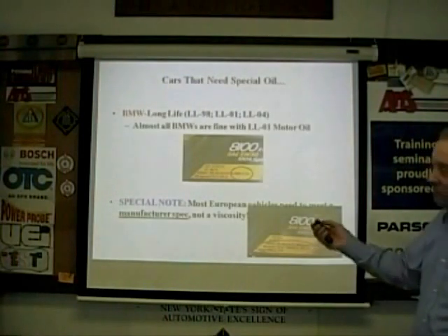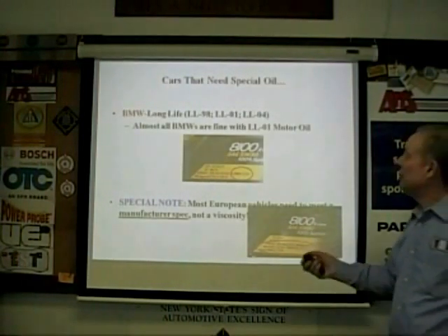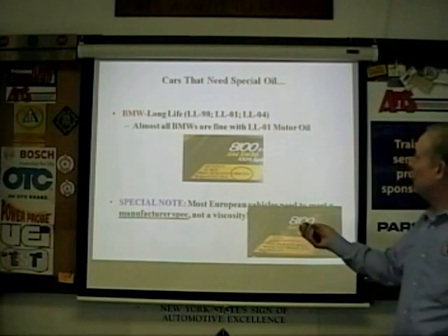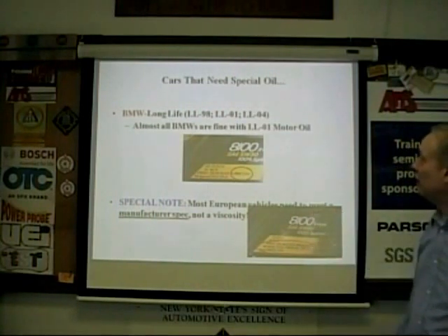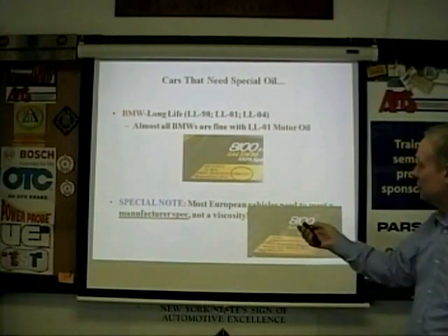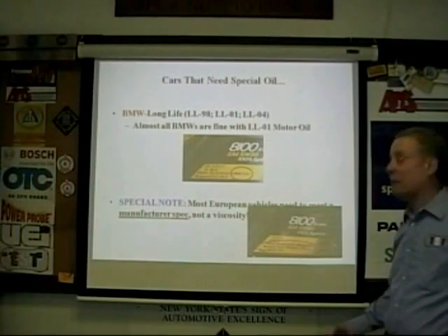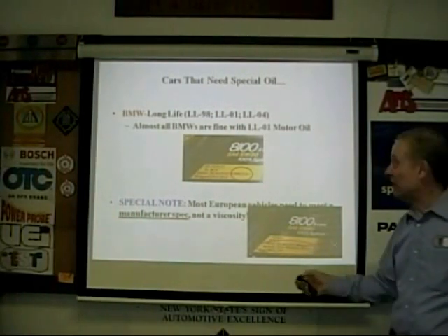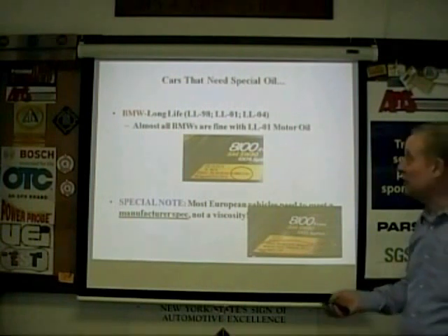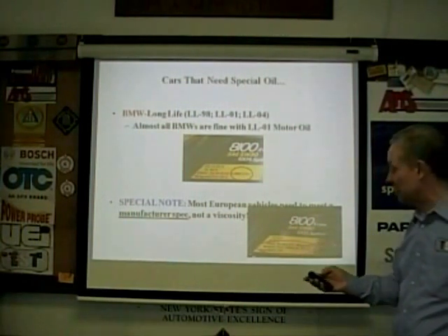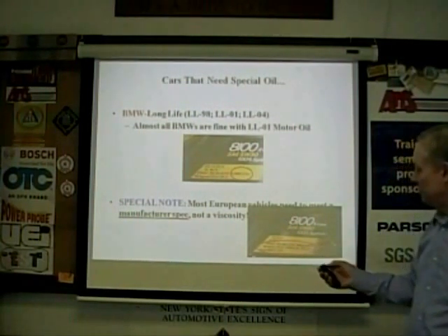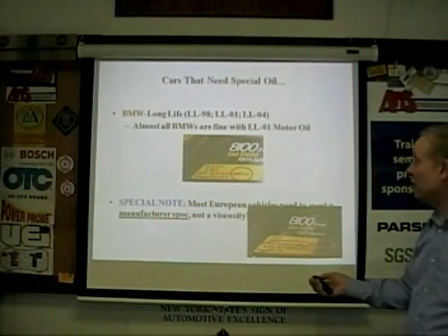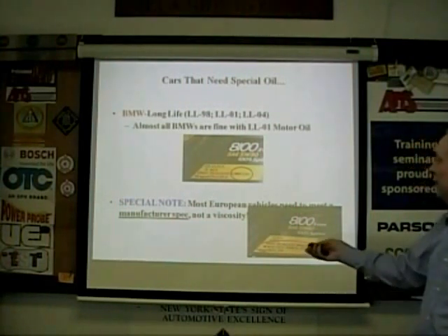Speaking of BMW, they have long life specs, LL-98, 01, and 04. What they don't show here is for their M motors, they also have a special spec for that. It's not on here. M motors need a special oil, 10W60 special oil. Again, read the specs for the particular car you're working on.